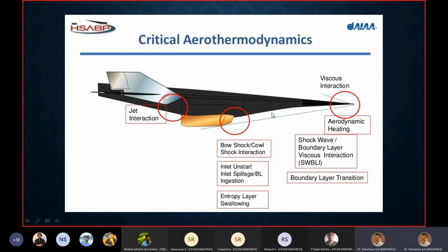It is found that when you have a planar body, the integration is easier, stability is better, etc., based on the laboratory tests. So though all our models are being studied, you tend to see more planar bodies or 2-dimensional or rectangular kind of structures in supersonic, hypersonic vehicles. It's more related to the aerodynamics and stability.